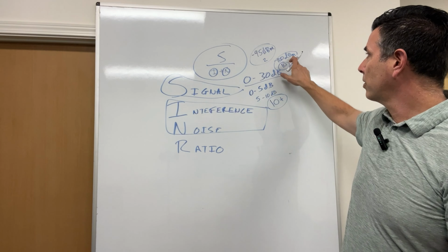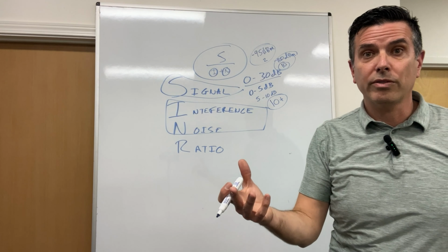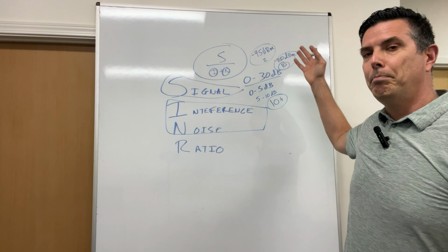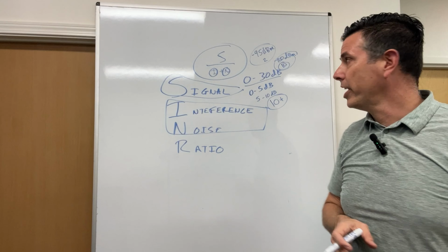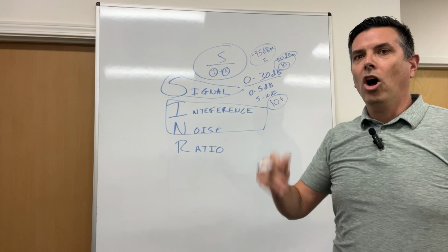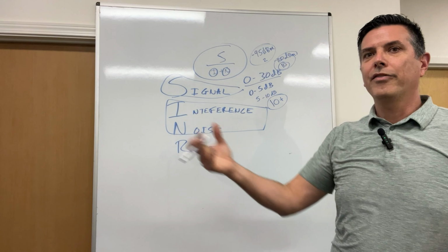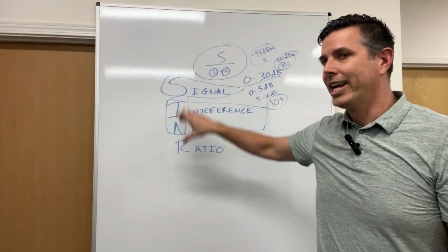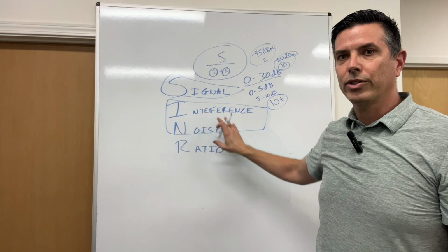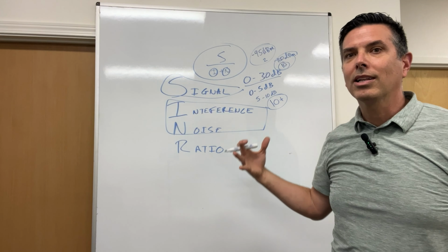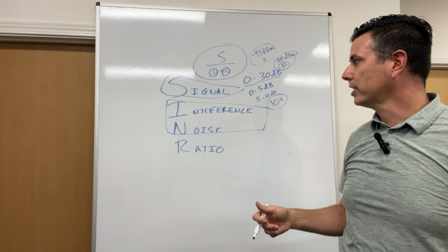As long as you meet the minimum thresholds for good service, neg 100 is okay. That better SINR is going to do you better on your network. But just remember, RSRP is that measure of your power coming in, and SINR, signal to interference and noise ratio, is how clean is it? How good is that signal?